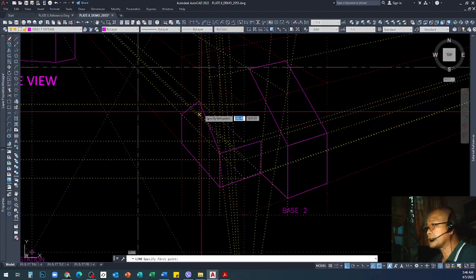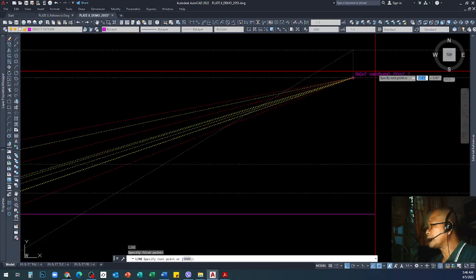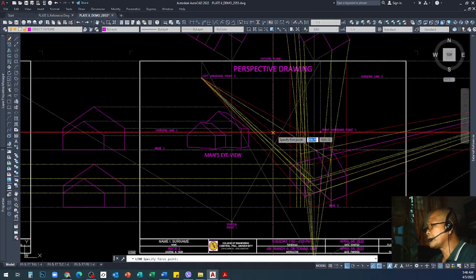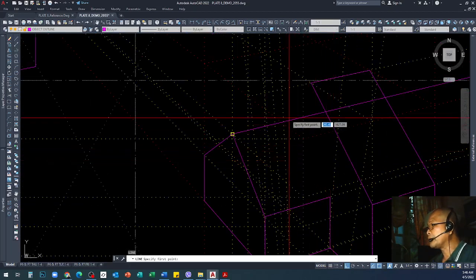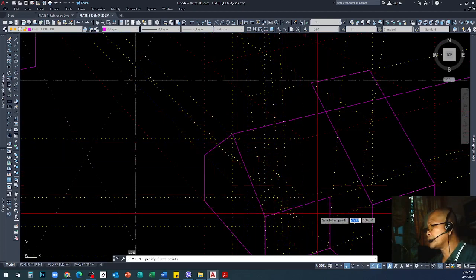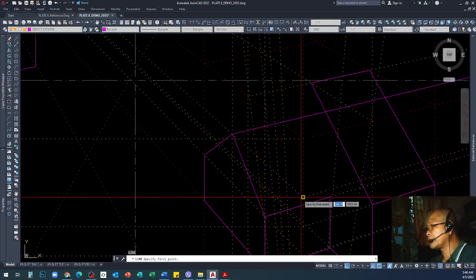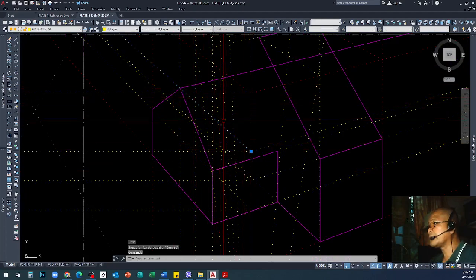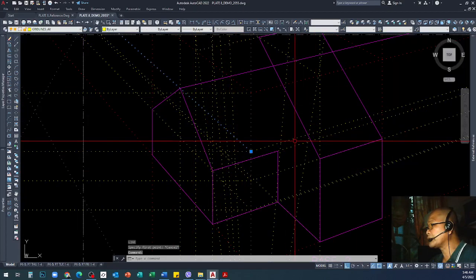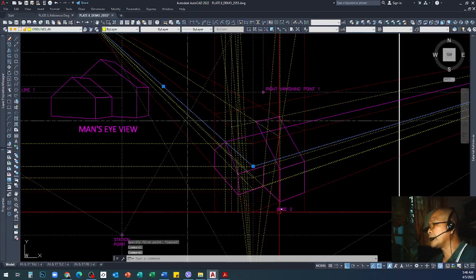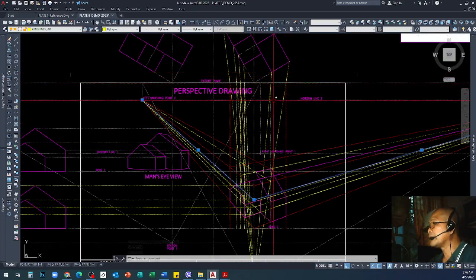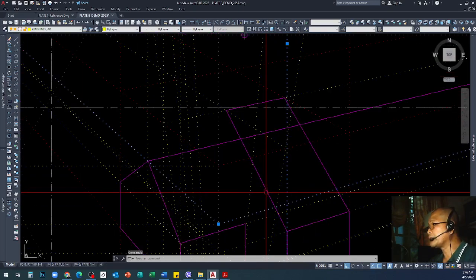Now we will establish where is the opposite of this one here. So by projection, we can use the tip to the right vanishing point, and then how do we know where it is here? Using the projected lines earlier. Okay, this is the line of the height, and then we project it to the right vanishing point, and it will intersect this line here that we projected.